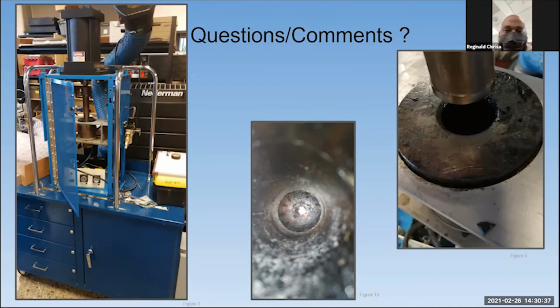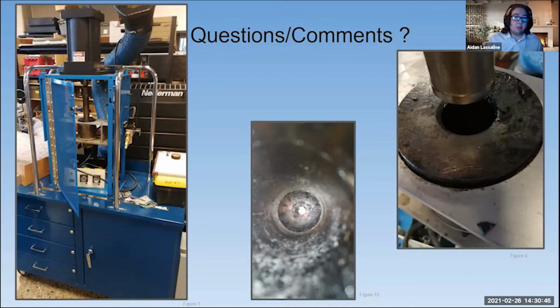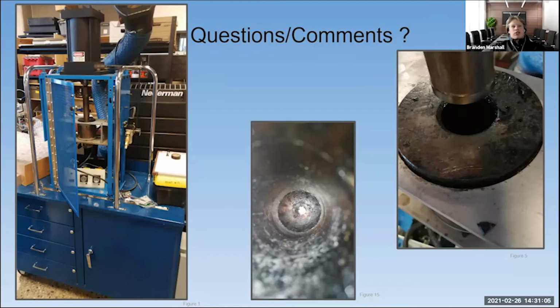So does that mean that there's another stage before this where they have to separate the different plastics in order to have consistency of product? You would need to separate them by their plastic type, but it doesn't matter what it is, as long as they're all type 6 plastic in the same hopper and they're pre-shredded to about the size of your fingertip, they will work together. Yeah, it's because the different types of plastics have different softening points. So if one is much lower, then it could turn into, as Brant said, basically molten and then off gas, which is really dangerous.